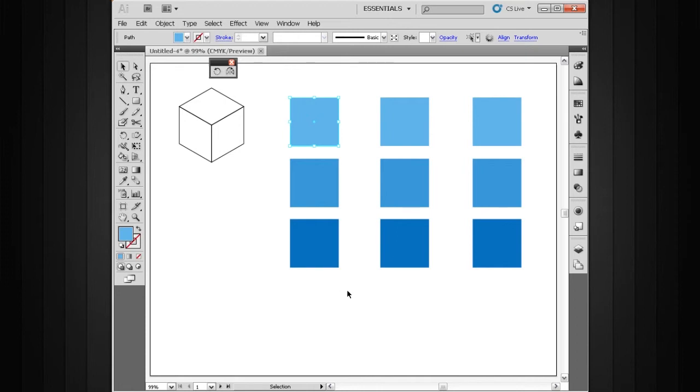And let's talk about which of these three faces we're going to create first. We need to know because whichever face we choose is actually going to affect the values that we input into each one of these different settings. So let's say we're going to attack this left face first here. And we need to talk about scale first. So I'm going to go over here and grab my scale tool. It's underneath your shear tool right here. And actually I'm going to snap that entire tool set out and bring that up because now we've got all three of those tools visible here.